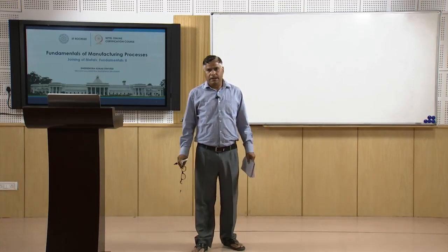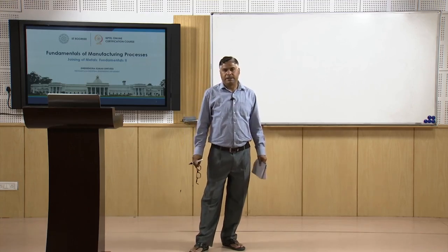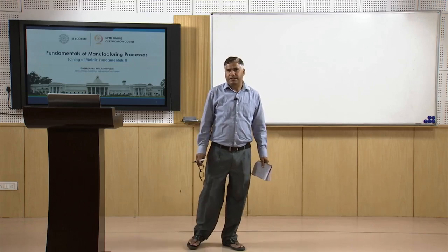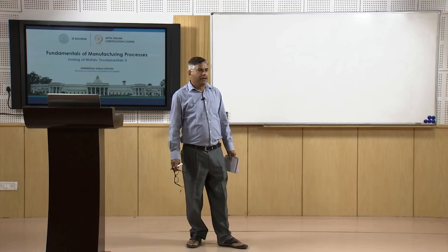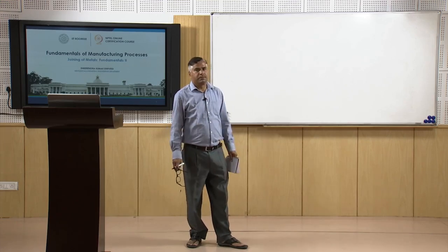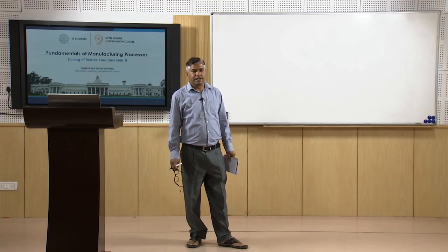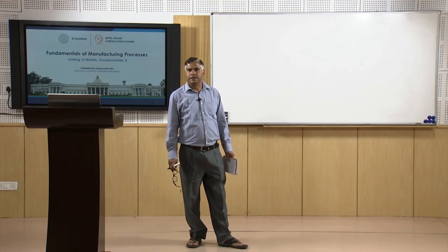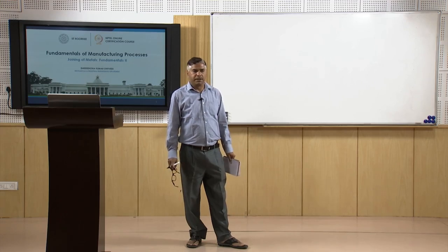In this presentation, I have talked about some of the basic aspects related to welding positions, the role of heat input in development of sound joints, and how power density affects the amount of heat required for welding. I have also talked about how the energy density varies in the heat source, which is maximum at the center and keeps on decreasing as we approach from the center to the surface of the heat source.